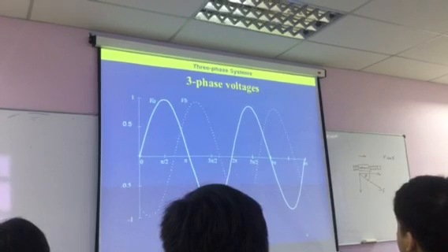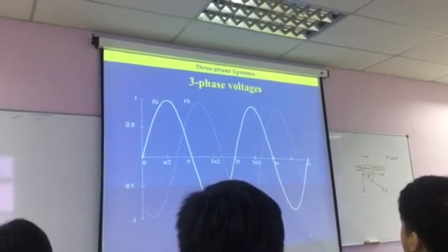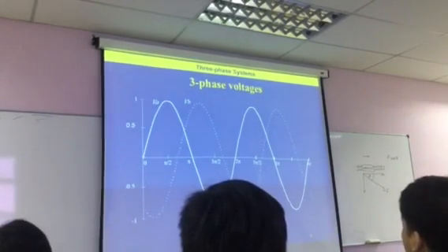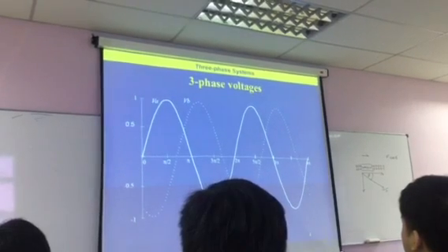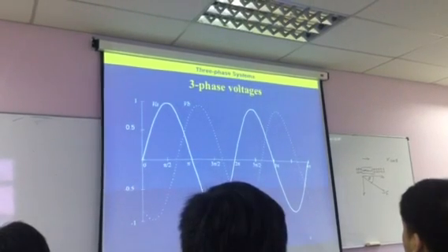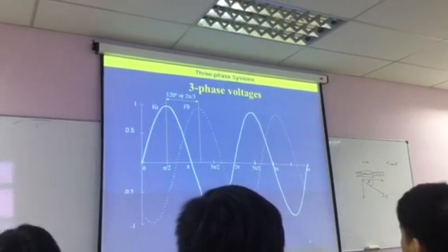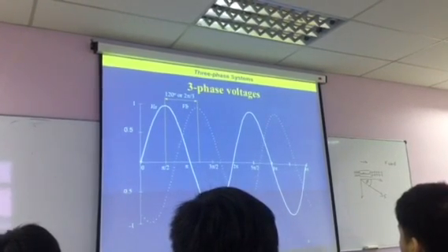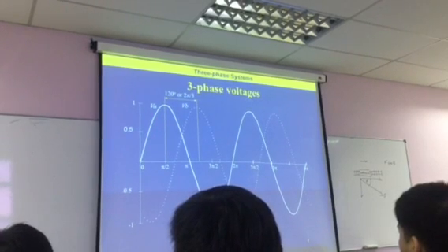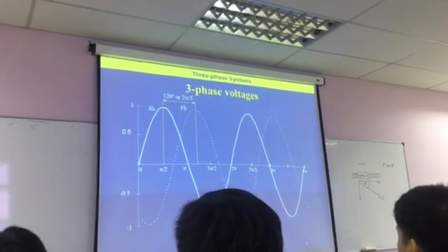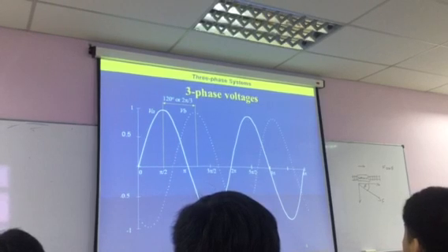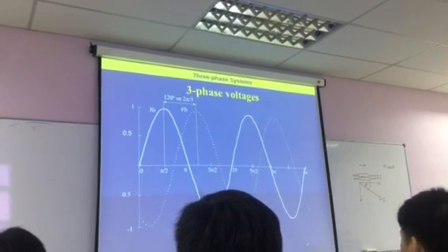What we can introduce is a second phase. So we've now got two voltages on that diagram, VA and VB. And just to look at what we have within there, they have what is called a phase difference, because you know the full 360 degrees, or 2 pi radians.